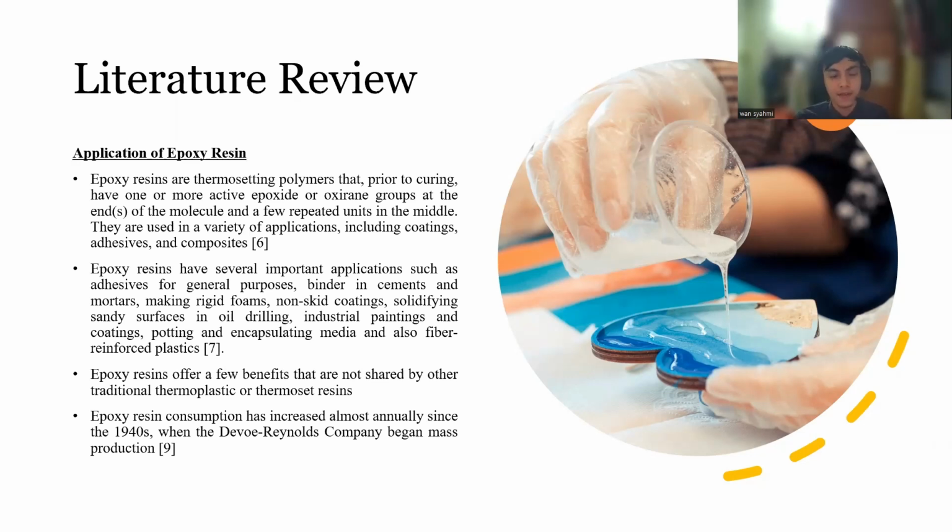Epoxy resins have several important applications such as adhesive for general purposes, binder in cement and mortar, making rigid foams, non-skid coating, solidifying sandy surfaces in oil drilling, industrial painting and coatings, potting and encapsulating media, and also fiber reinforced plastic. Epoxy resin offer a few benefits that are not shared by other traditional thermoplastic or thermoset resins. Epoxy resin consumption has increased almost annually since the 1940s when the Devoe Reynolds company began mass production.